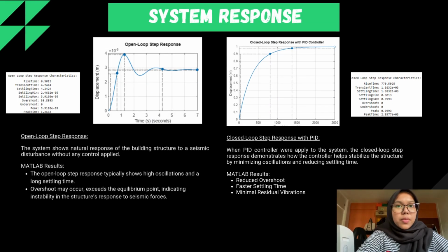Next, I will explain about the step response. Firstly, open loop step response. The system shows natural response of the building structure to a seismic disturbance without any control applied. The step response represents the building displacement over time due to a sudden force.